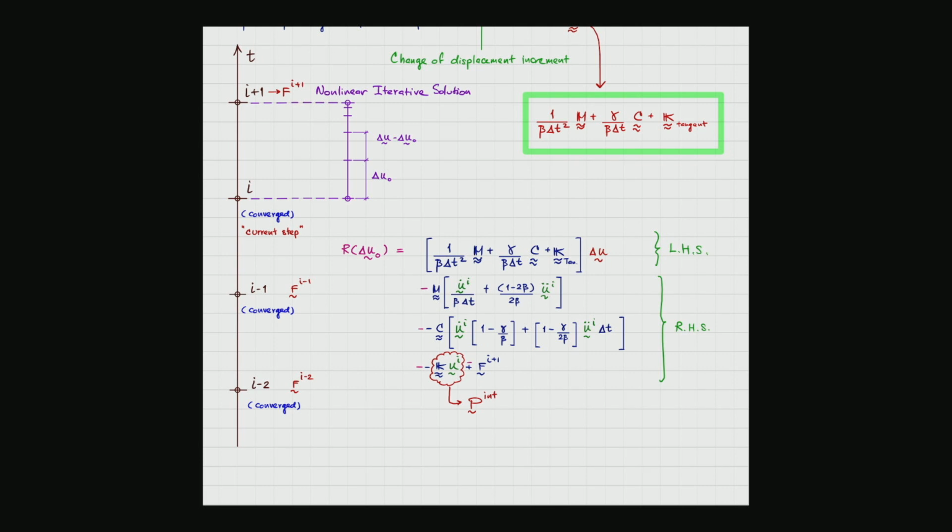That's one thing. And another thing, you might change from the implicit time integration into the explicit time integration. You chop down the time stepping size into a much smaller one because the explicit time integration is prone to stability issues, instability. So you can end up with a problem in the analysis. You can end up with an unstable calculation, and it stops. It gives you the bursting out of the solution. It blows up.